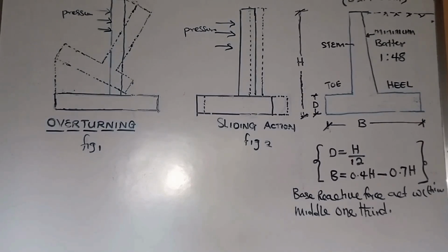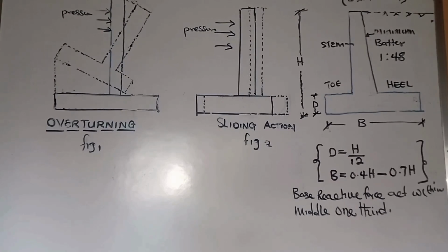We can as well ensure that, for the selected base, the reactive forces acting on the foundation are within the middle third, so that we won't have too much stress on the toe. A section that will induce more stress on the toe should be avoided as much as we can. So we must ensure that our base reactive pressure lies within the middle third. So that is that for the base.